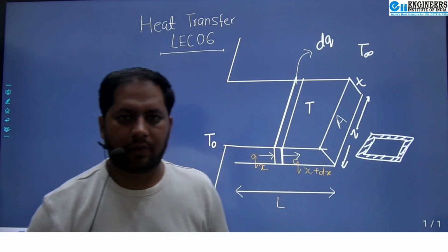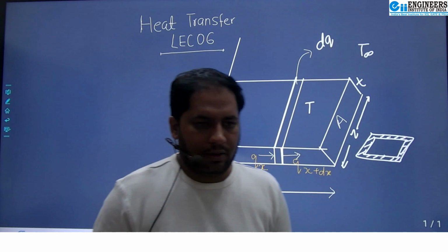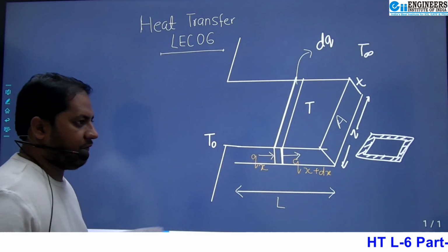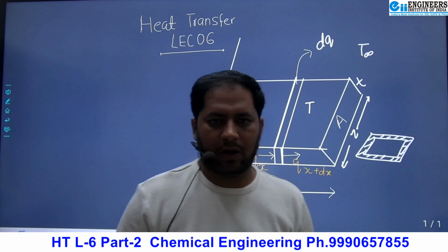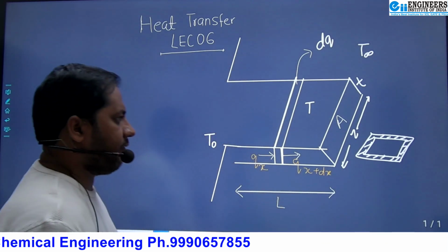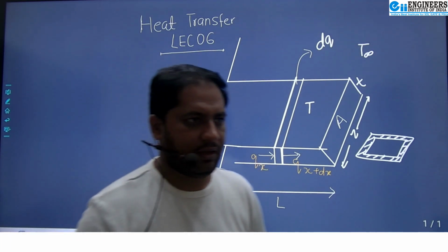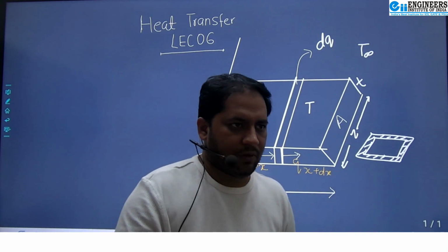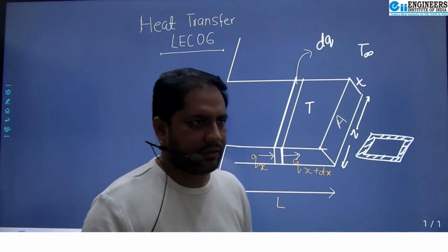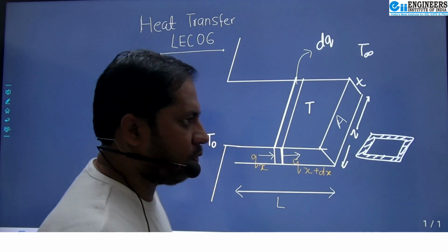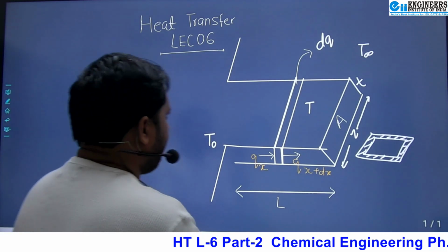So in continuation of our lecture 6, we are discussing the rectangular fins. In lecture 6 we discussed that fins have many applications that keep equipment from overheating. At the base, or at the body of the equipment, the fin is connected in such a way that extended surfaces are provided, and when air is in contact with this extended surface, additional heat is convected away and cools the temperature of the body of that equipment. So now if we take a rectangular fin,